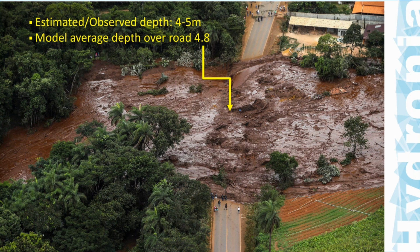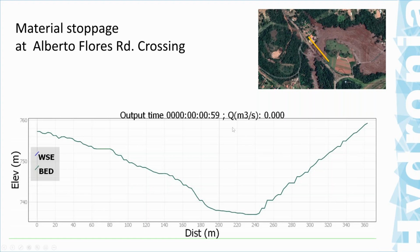This is a tailings deposit mixed with the erosion that this deposit caused in the bed, and that's what you get there. So you have to remove that. It doesn't happen with water ever. Now the estimated or observed depth at this location is between 4 or 5 meters, and we got approximately 4.8 on this average area. So we come very close to those values here.